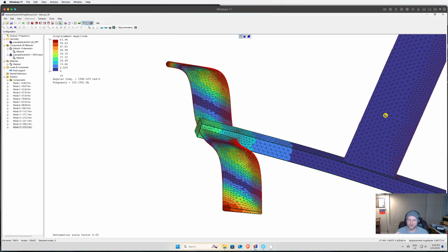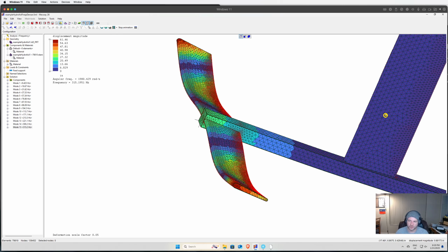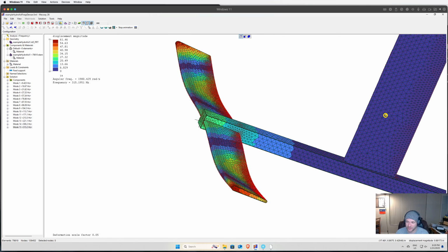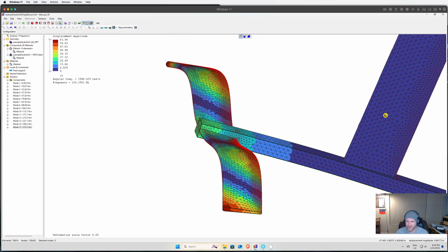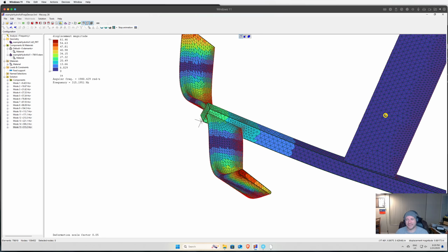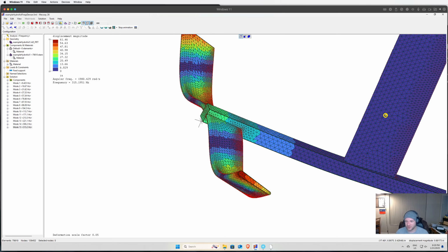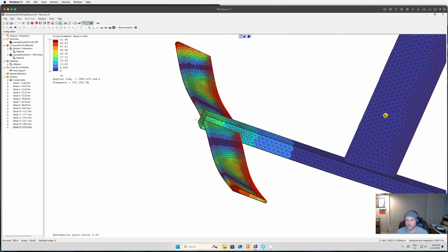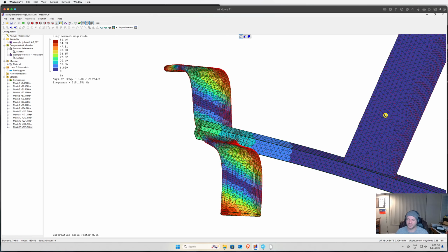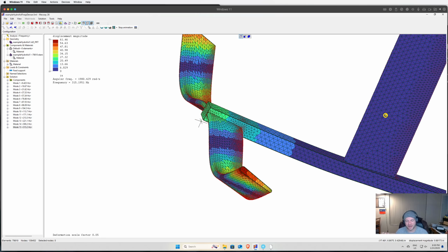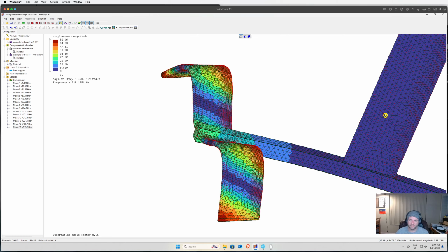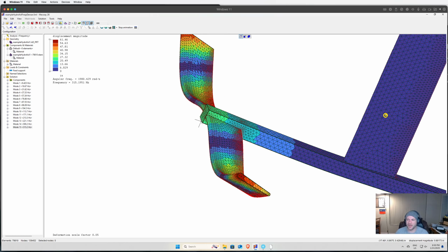Unless you're sizing some kind of lifting feature where you're lifting something that has to be a certain strength, and strength determines things. But a lot of the time it's stiffness. For functionality of mechanical components, it's almost always stiffness. Like cars, you worry about the stiffness of the suspension, the stiffness of the springs, the engines, the stiffness to certain things. I mean, strength does matter, but you have to look at both. You can't just look at strength.